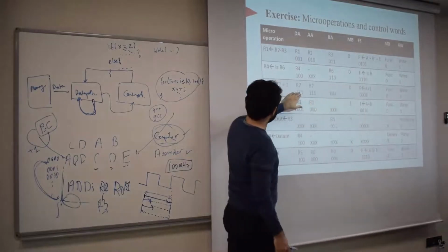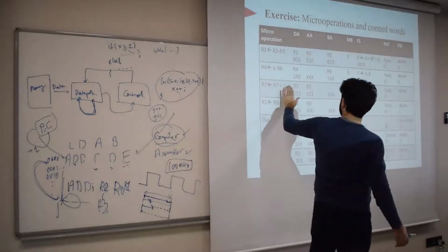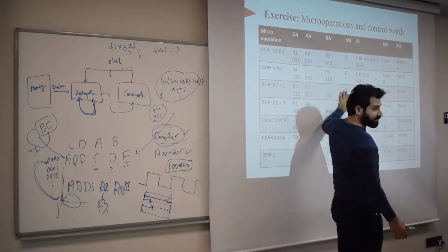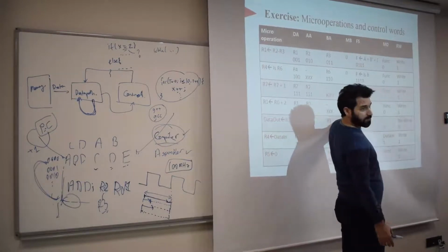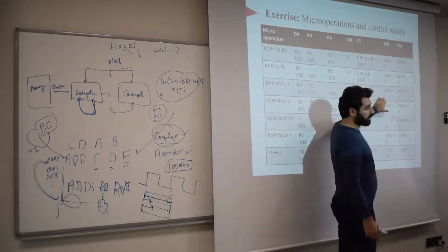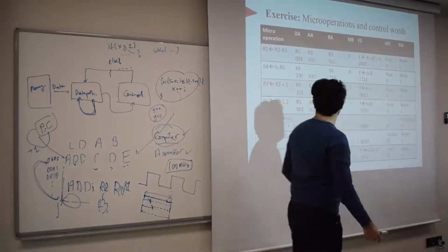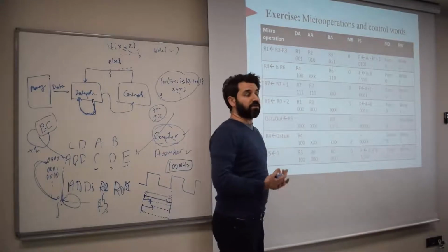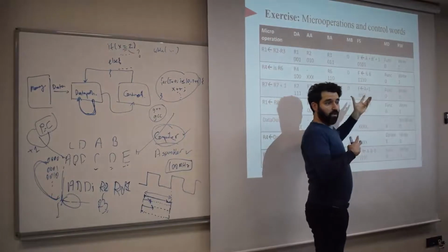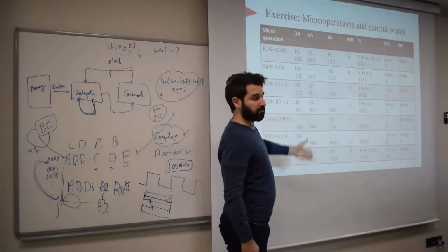So I use that. So this is R7 again, and this is don't care. Okay? Because we don't use B, as you can see. MD is 0 because we're not really getting any constant. Okay? This is the function unit that helps us implement incrementation. This is 0 because we're not getting anything from the memory or writing something to the memory, and we write the destination. Okay? And as I said before, it's not unique. You can actually set MD to 1 and push that 1 as a constant, okay, as part of your instruction. And that would also do it.